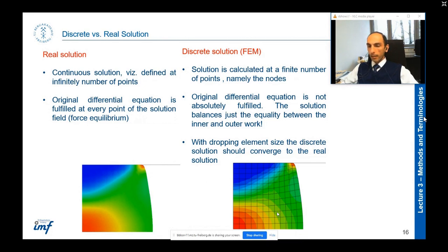And after, I can say, a critical value, the dependency of the result on the mesh size becomes very, very low. Of course, if you increase the mesh numbers more and more, the result improves, but that improvement is not too much, so you can find that critical value for the mesh, and then you can continue your study with that critical value.